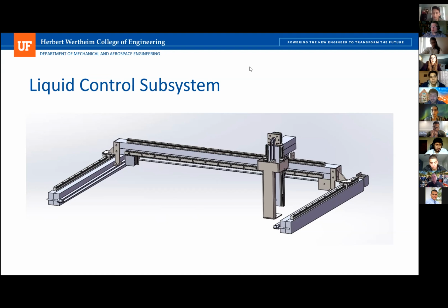My thought would be that the rails, which is what they're mounted on, could be mounted before the assembly is welded together, putting them close together and using something like a parallel, like we use in DML, to line them up and make sure they're parallel to each other, and moving it along the length to make sure that it attaches properly. So that would probably be the best thought we've got.